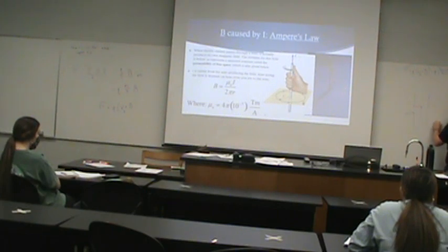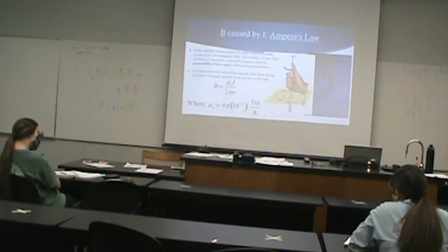One thing we don't do is put wires across one another, because then you're going to get perpendicular overlapping fields. Because for these wires, the field will be spiraling in this plane. For this wire, the field will spiral in this plane, and that's when things get really bad. So as often as possible, lines are kept parallel to each other. If a wire has to go perpendicular, you put it somewhere else on the board with the other perpendicular lines.